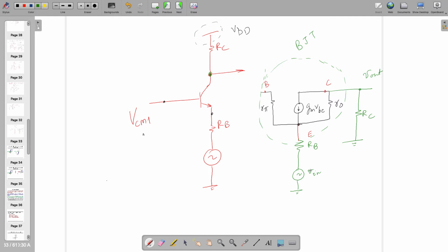And if there are multiple sine waves, I'll give another circuit afterwards. Okay, what about the base? Base is connected to common mode voltage. So what should I do? Look, R pi side, Vishal. R pi positive terminal is floating right now. So what are you supposed to connect there? VCM. Common mode is DC. So DC, what am I supposed to do here? Ground, because it's AC ground. You understand or not? Okay.